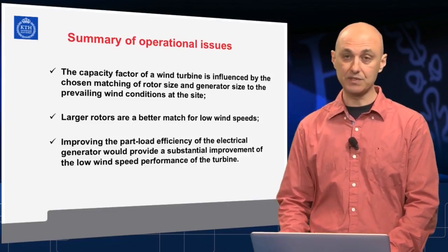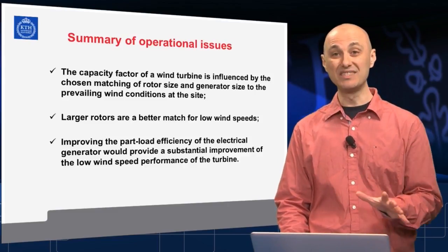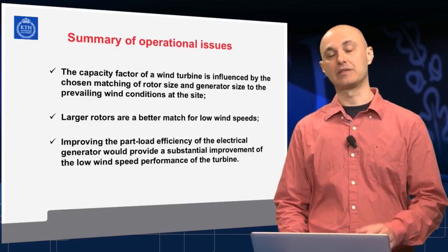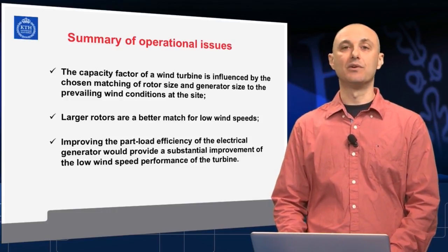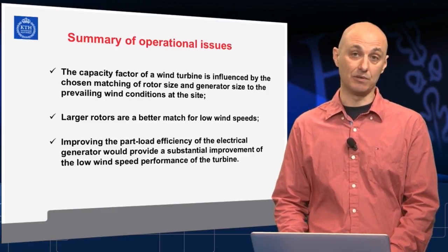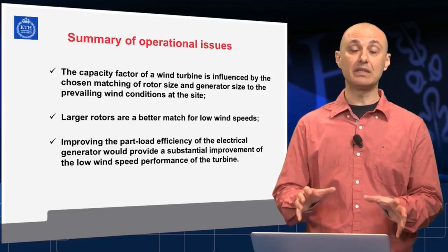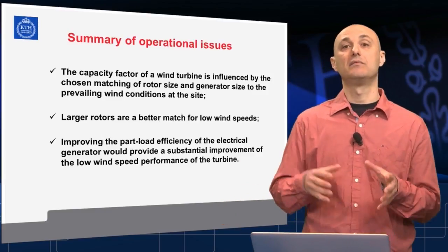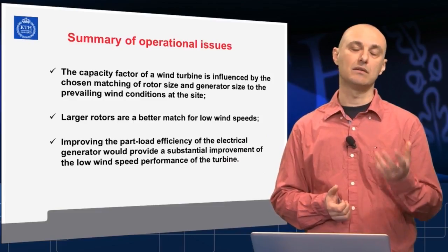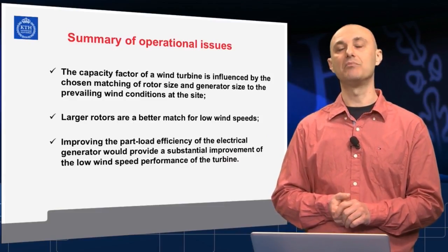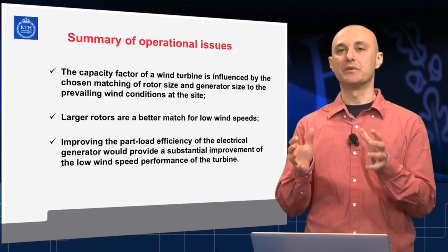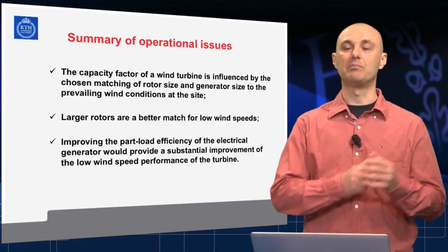Improving the part load efficiency is very important, both for the wind rotor aerodynamically and for the electrical machine, the electrical generator. There is no machine that is able to work efficiently at deep partial loading. And improving the electrical aspects, both generator and related power electronics, regarding deep partial loads is very important. You can harvest a lot more power if your generator is efficient at part loads.